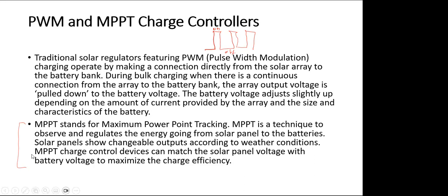This is a very efficient concept. This concept needs to be used for grid tie type technologies. If the solar panels need to be connected to the grid, maximum power point tracking needs to be used. If it is connected to a battery for a small system, pulse width modulation type is used, maybe for a household system. Even for battery charging there are maximum power point tracking controllers. However, for small systems, maybe cost is a factor. That's the reason pulse width modulation type charge controllers are used there.